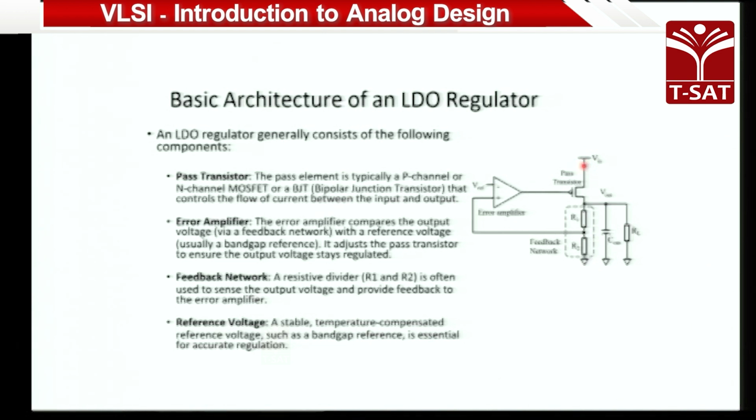There will be a resistor connected here. However, you cannot envision that, because that is not in this particular model. Once you do a post layout simulation, that time you will see these resistors, these capacitors. Now, there will be another capacitor here that will add additional poles and zeros and all those stuffs, right? Like poles, zeros are again coming from control theory, right.